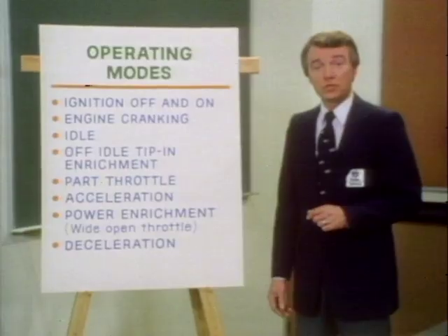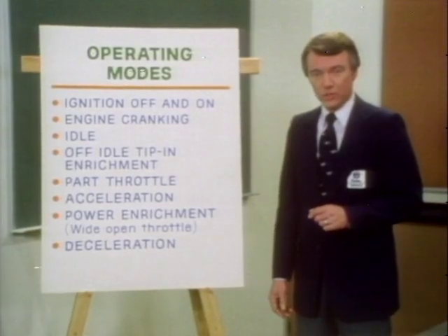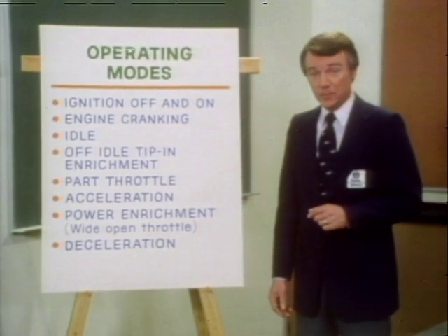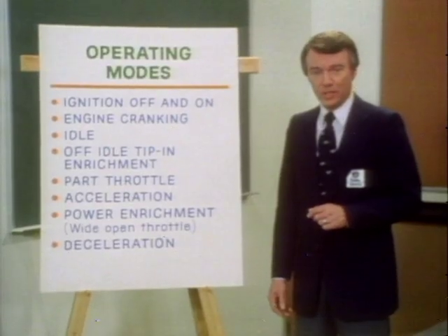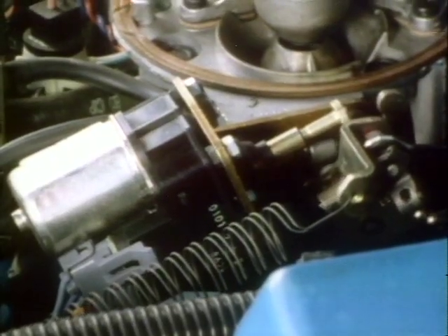Once the engine enters closed loop or warm engine operation, the influence of coolant temperature on pulse width and spark timing is reduced. Since the driver is in control of the throttle, the ECM issues a command to the ISC actuator, retracting the plunger, preventing interference with throttle operation.